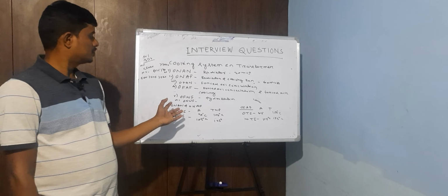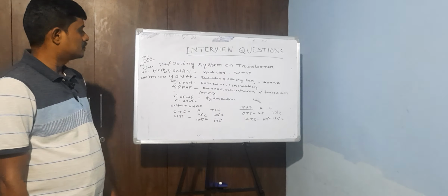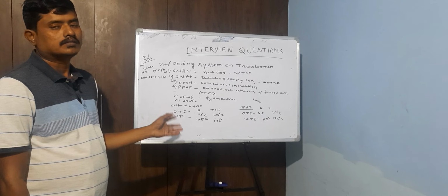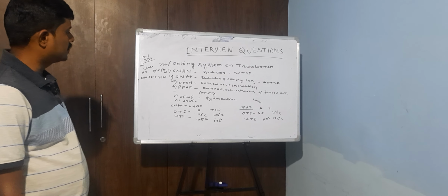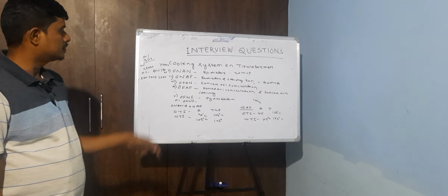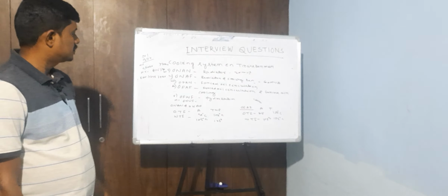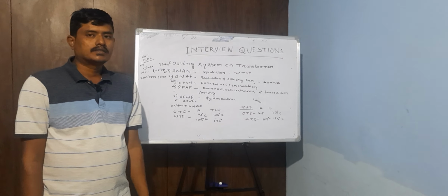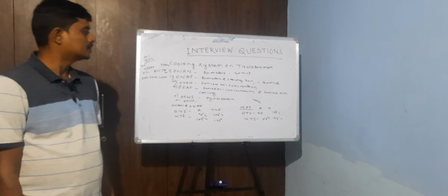Then accordingly, as per the cooling system, the OTA and WTA settings also change. When you use ONAN and ONAF, at that time the OTA alarm setting is 90 degrees centigrade, trip setting is 105 degrees centigrade, then WTA alarm setting 105 degrees centigrade, trip setting 135 degrees centigrade.